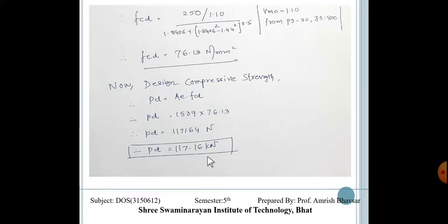Okay. Whenever we have this kind of case, we can calculate this FCD in another way, but it is applicable only when our load is applied concentrically. So you can see, concentrically applied load is given in this case. So we can calculate that FCD directly from page number 42 for the class C, from KL upon R. Let's see.